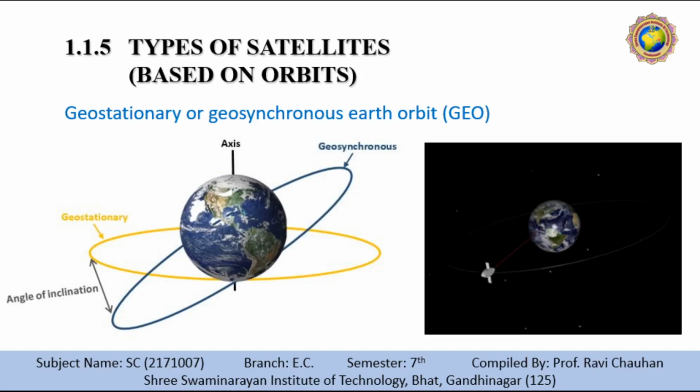Let's discuss. The northern or southern regions near the Earth's poles have more problems receiving these satellites due to the low elevation above latitude of 60 degrees. Larger antennas are needed in this case. Shading of the signal is seen in cities due to high buildings and low elevation further away from the equatorial limit, affecting transmission quality. The transmit power needed is relatively high, which causes problems for battery powered devices. These satellites cannot be used for small mobile phones.